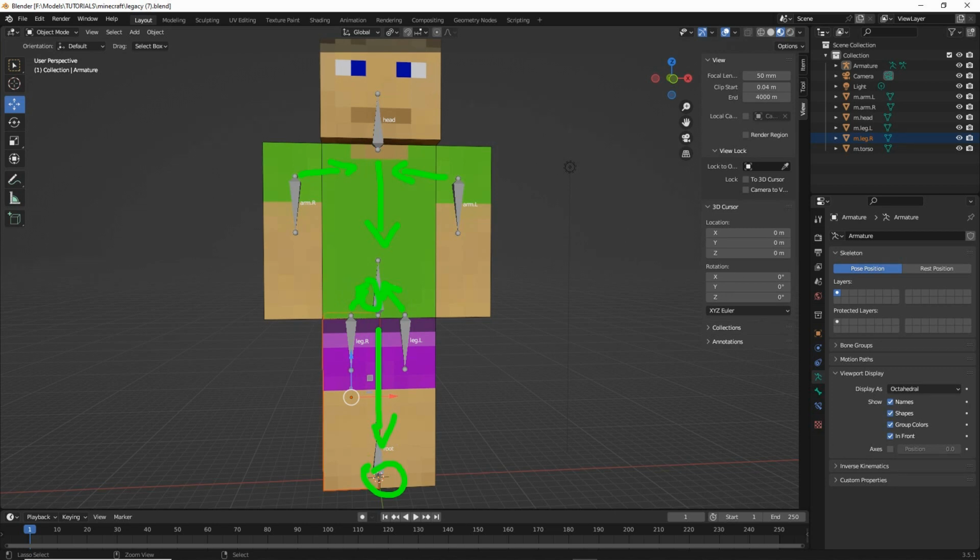Doing that, however, will result in all the parts, the components, acting independently of each other. So there'd be no relationship between the torso and the arms. They would move independently of each other. Typically then, we would want to use the torso as our sub-root and then link that to root as the root.